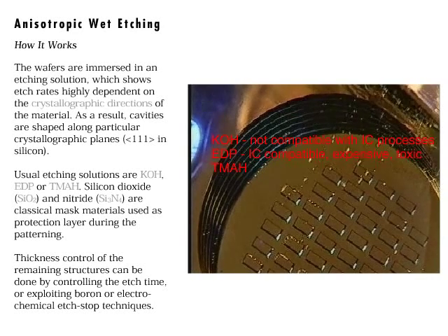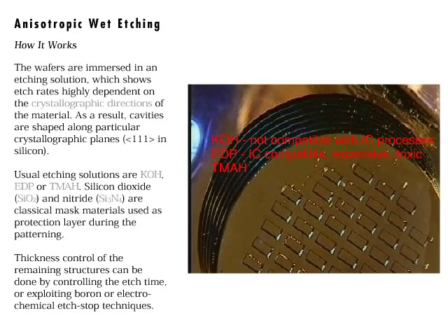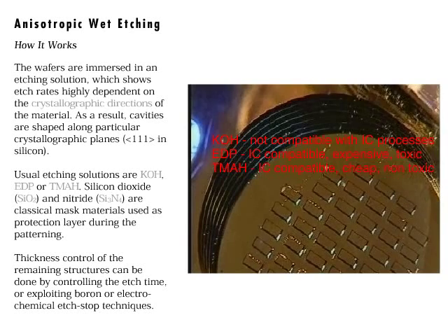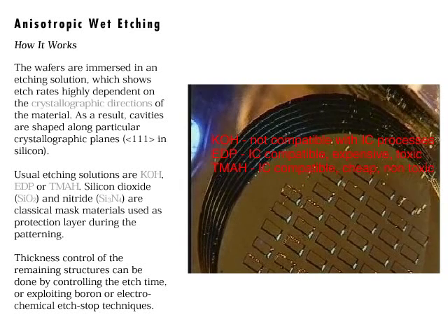Tetramethyl ammonium hydroxide, or TMAH, is used more and more as etching solution for anisotropic etching of silicon. It is non-toxic, IC compatible, and low cost.